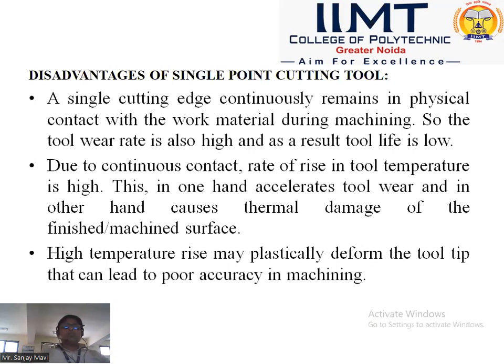Why? Because the cutting edge of single point cutting tool continuously remains in physical contact with the workpiece during the machining. So the tool wear rate is very high, and that results in low tool life.